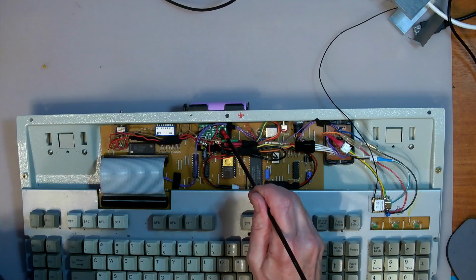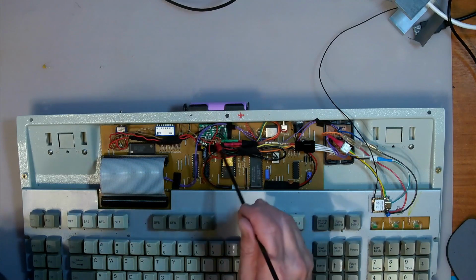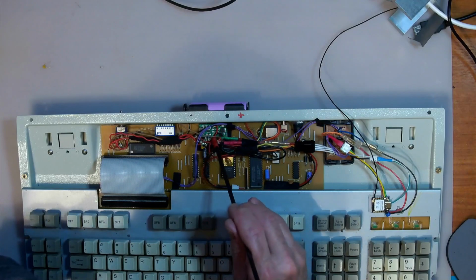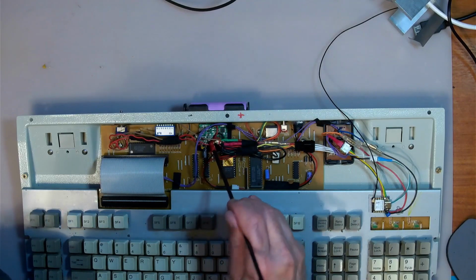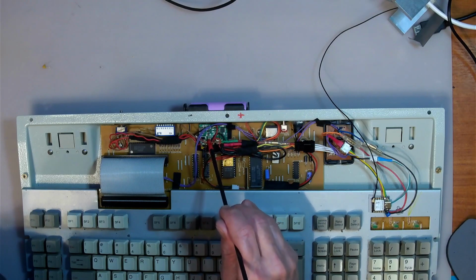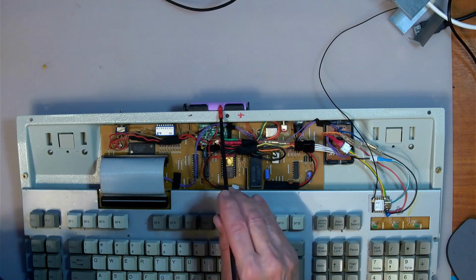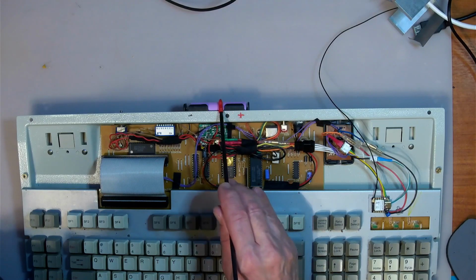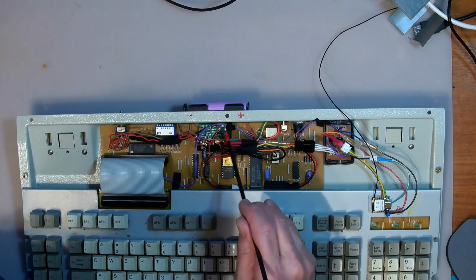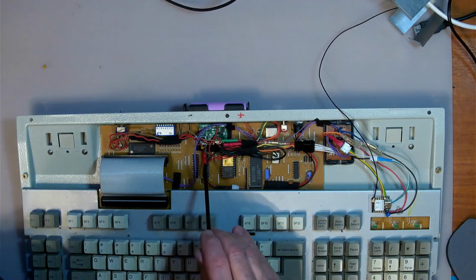This thing can actually charge the lithium-ion cell, but it can also power something. There's a tiny trim pot in there. You can actually set the voltage to different voltages, but I got that trimmed in order to output 5 volts. And so the 3.7 to 4 odd volts coming from the cell here gets turned into 5 volts. There's a boost circuit in here, and I put a couple of extra capacitors on there.